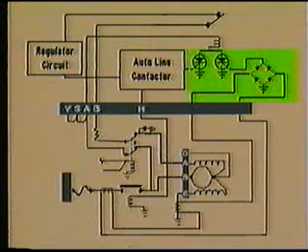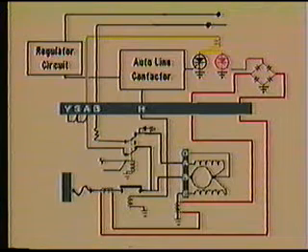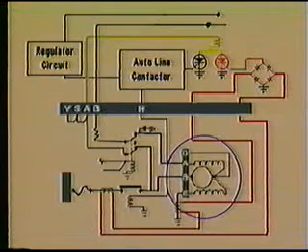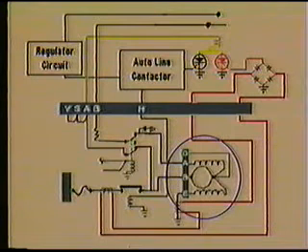The feeder fault circuit is the same circuit as used in the battery fault system. Feeder fault transformers installed in the generator power and ground lines are connected to a diode bridge within the generator control panel. If a fault is sensed in this wiring, the SCR in the circuit will conduct and cause the trip relay to open, thereby disconnecting the field lead of the generator. The main contactor circuit can also open the trip relay via this other SCR if it senses an abnormality in the generator output, such as incorrect generator polarity or overvoltage.